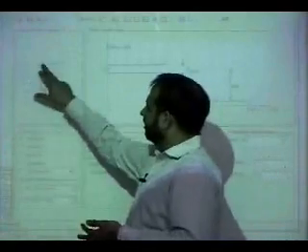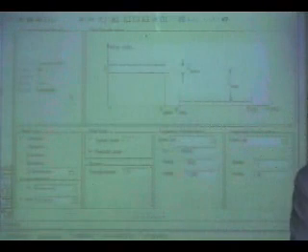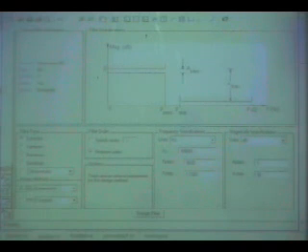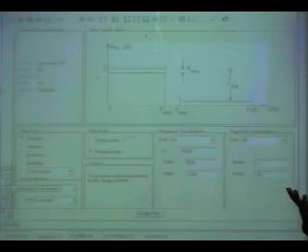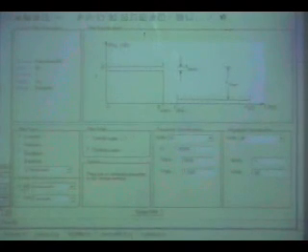Then you specify what type of filter you want, an FIR or an IIR. Because we have covered an IIR, you say an IIR filter. So this is an IIR. Even if you are mapping it on a fixed point processor, you can in fact use these as well. You can set the quantization parameter. You say, I want these coefficients to be in 8-bit, 16-bit, 22 bits, it is up to you, because MATLAB designs in double precision format. So you can always come and say, I only want the filter to be in this format and only 8 bits. You may spend some time learning about this, but here is the IIR.